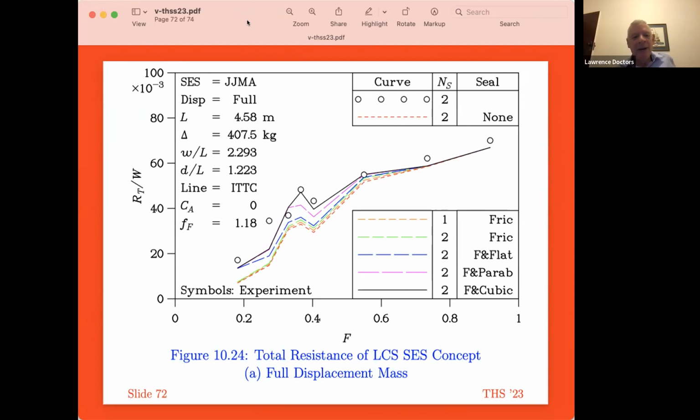Okay. So in this theory, that's a very good question. I have to think for about 2 seconds. In this theory, the pressure drops off instantly on the sides because you've got the side hulls, but at the ends, I've used some tapering off of the cushion pressure as you've suggested. So the pressure does not drop to zero suddenly at the two ends, namely the bow and the stern.